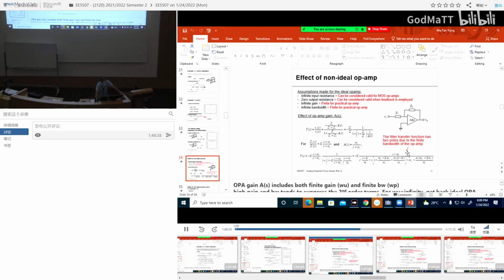So now we have this circuit, an inverting amplifier configuration, with Z1 and Z2. Now if we analyze it with a real op-amp with a finite gain A, we can do the same analysis, but now you see in the transfer function, A comes in already. Why does A come in? It's because this input difference is V out divided by A. Remember, in the ideal op-amp, we assumed that A was infinite, virtual ground. Here is ground, here also ground.